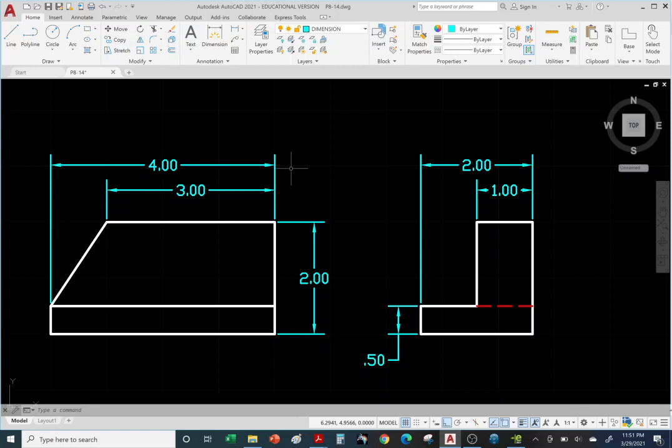So when dealing with holes where you want a tight fit diameter and control it, you will go to 3 decimal places on the diameter of a hole, and maybe even up to 4 decimal places. But typically 2 decimal places is the way to start, and then you can work your way to 3, maybe 4 decimal places, depending on the function of the circular hole, depending what type of fastener you're going to put, whether it's a bolt, a dowel pin, etc.